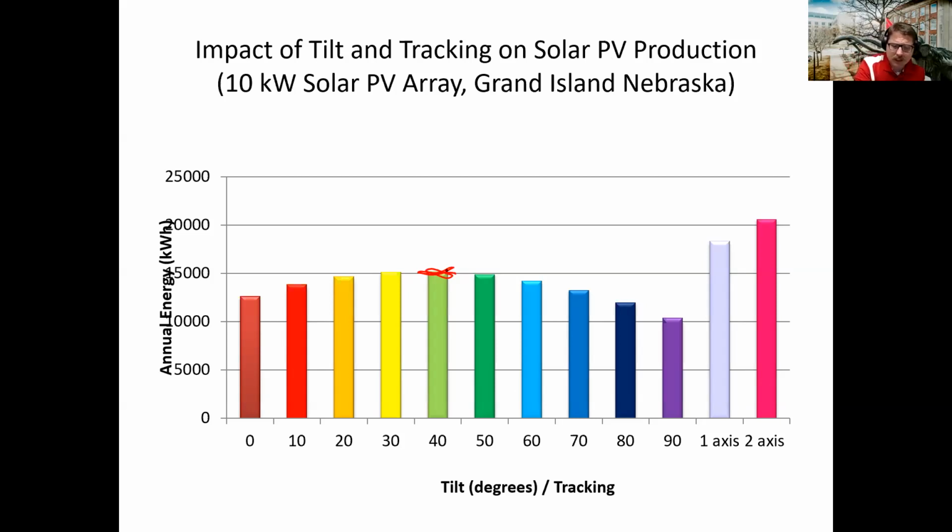But you can also see that the tilt angle is not real sensitive; even the ones that are 10 degrees different are only down by about a couple percent. So tilt is important, but it's not real sensitive. If you don't have an optimum tilt and you're suboptimum by 10 or 15 degrees, you're still generating 96 or 98% of what you would with an optimum tilt. So tilt is important, but not super. You should not spend a lot of money to get that optimum tilt. That's what I'm trying to say.